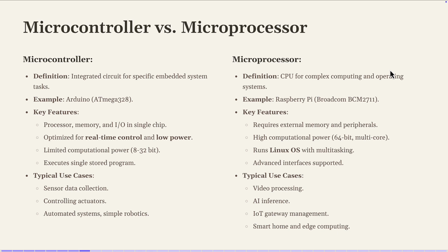So in robotic applications, we typically have a microprocessor to interface with users. For example, the user would say, I would like to move 2 meters per second in the straight direction. Okay? So we provide the velocity at the microprocessor level, and then it goes to the microcontroller, which is attached directly to the hardware. And from there, we convert the velocity that is sent to a signal to the right motor and a signal to the left motor.